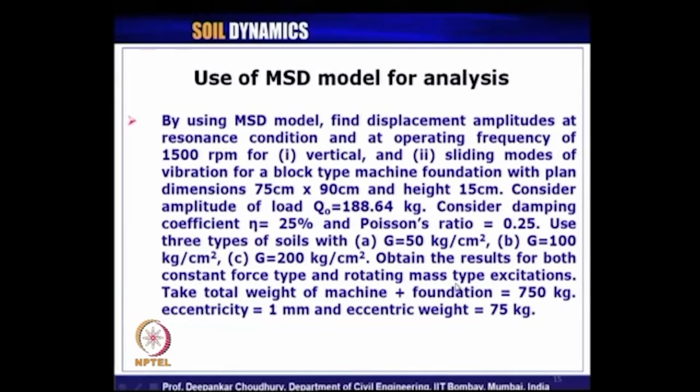In our module 2, vibration theory, we have seen that for the mass spring dashpot model, for any machine foundation, we can have two cases. One is when the machine is subjected to a constant harmonic load, which is called a constant force type machine foundation, and another is when there is some imbalance present in the system. Because of some rotating component, we can also get a dynamic load on the system. So for rotating mass type excitation also we need to find the displacement.